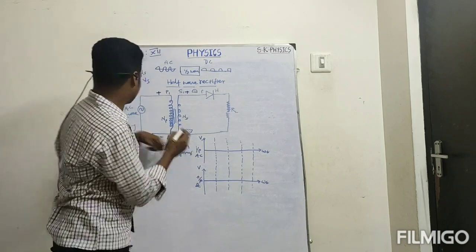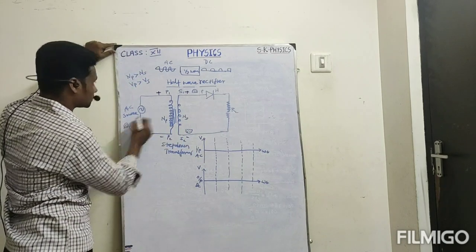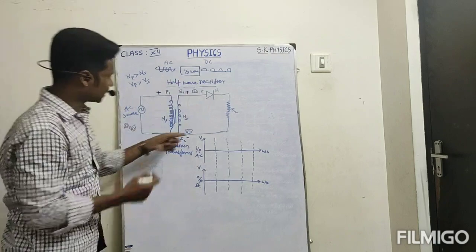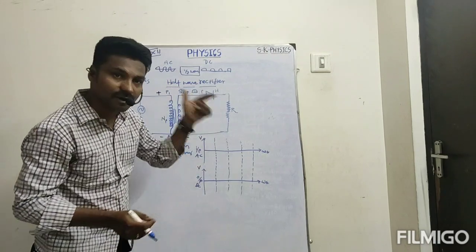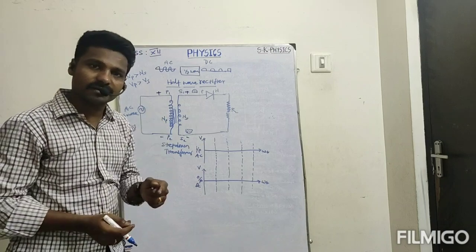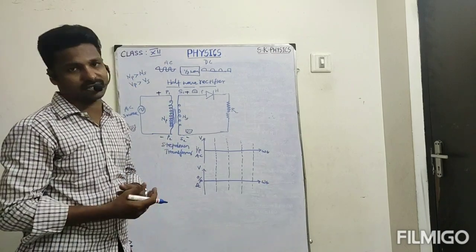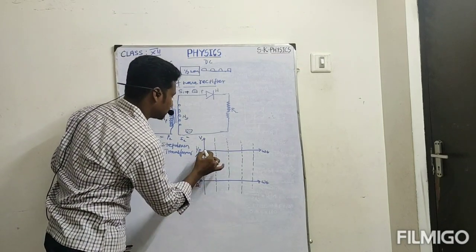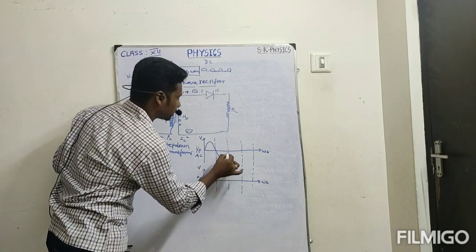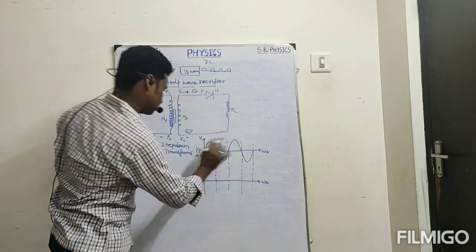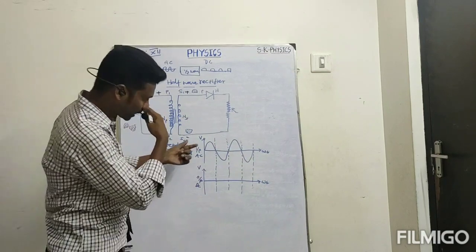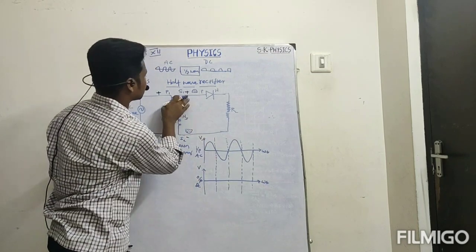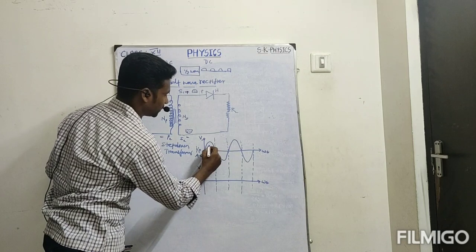See this wave, for example, the positive wave here and the negative wave here. So positive, negative to negative, now it is acting as forward bias. In forward bias, the diode offers low voltage drop and allows the current. So this is the input signal, positive, negative, positive, negative. We have to analyze inch by inch, for every cycle. Now let us imagine a positive cycle is running, so now the diode is working.